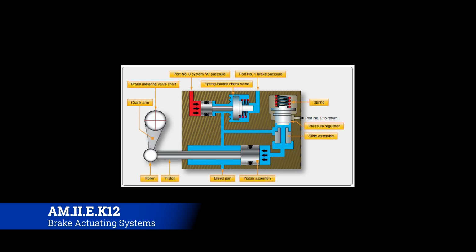On, say, a 737, you're going to have some pretty advanced brake packs, and we'll get into that in just a little bit, including what is actually on a 737 Max. On the other side, you have accumulator air pressure. So the shuttle valve can essentially say, "Hey, look, hydraulic systems have failed, so we're going to take emergency bleed air and use it to help stop the brakes, so that the plane doesn't go cartwheeling out of control." But that's basically how a power brake system will work on a heavy commercial aircraft.